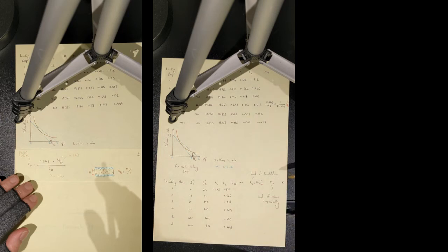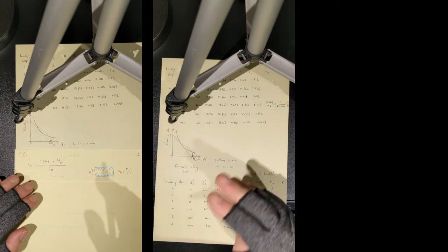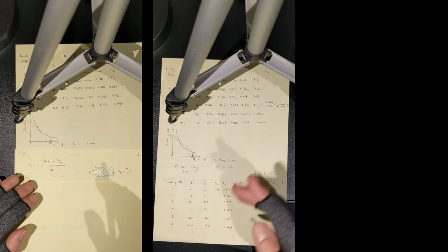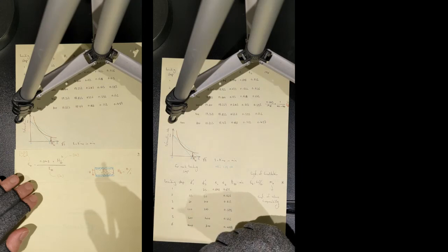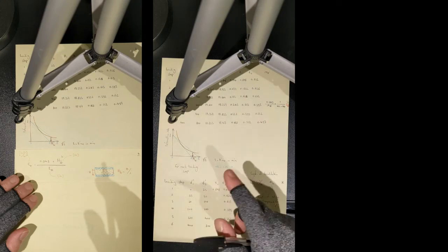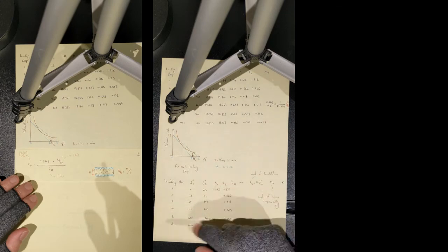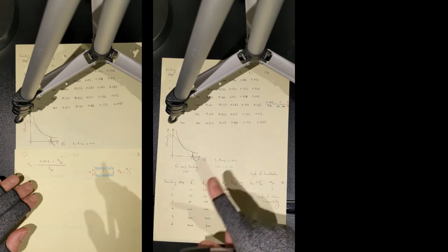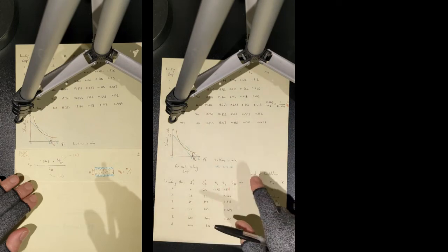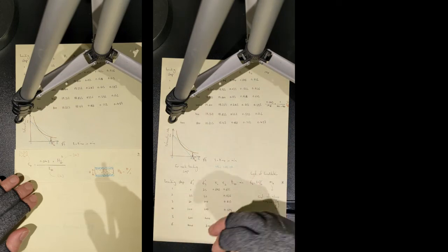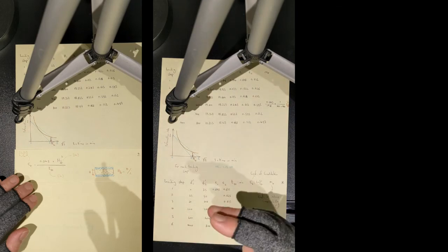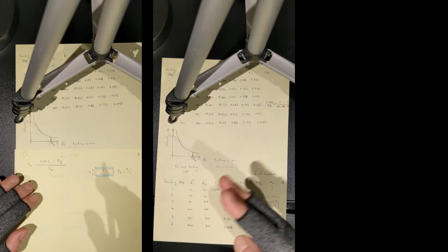You have two ways to go around this problem. One, to do another test which is known as falling head test, and I taught that in my tutorial. But I said I normally do not choose to do the falling head test. I instead choose to do the oedometer test, because the oedometer test can help you to calculate the amount of consolidation settlement beneath foundations and the time which it takes the full amount or a proportion of that consolidation settlement to happen. And at the same time, it can help me to measure the permeability of the soil. So, well, you can see how useful an oedometer test is.